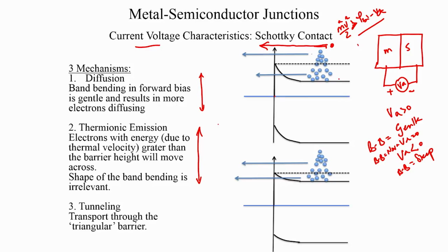So, we just see how the flux from right to left is affected by the applied voltage and how the flux from left to right is affected by the applied voltage, and the effective flux is the difference of these two. And if that effective flux is affected by the applied voltage, then definitely you will have a current, and that current is something called thermionic emission.